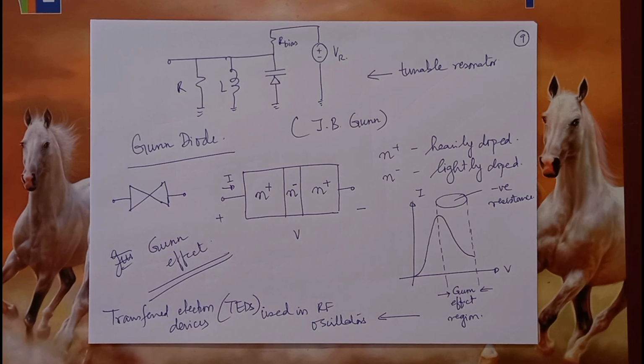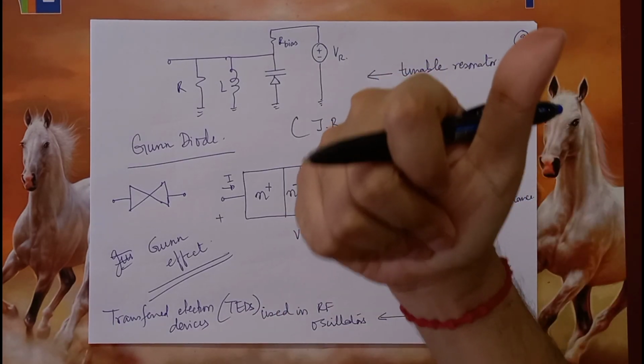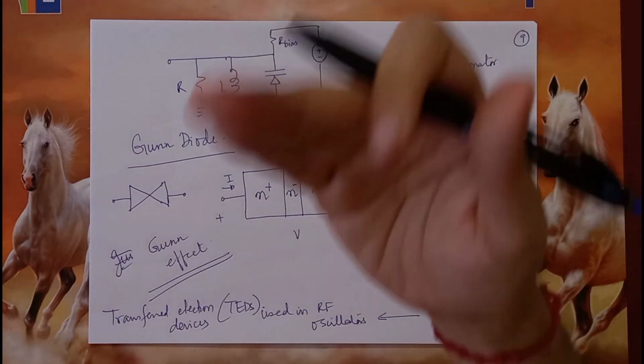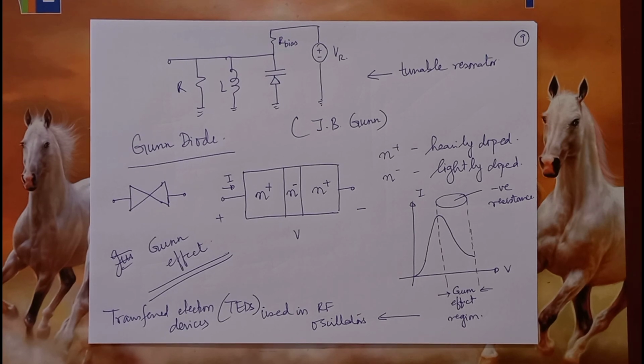So in the last lecture and this lecture, we looked at broadly 4 categories of diodes. We looked at the PIN diodes, which are used for switches. We looked at Schottky diodes, which can turn on and off very easily, but they are not used for switching as such because they conduct more in the reverse bias. But Schottky diodes exhibit lower built-in potentials and lower reverse recovery time, which make them ideal for use in low power detection and in places where the on and off has to be very quick.